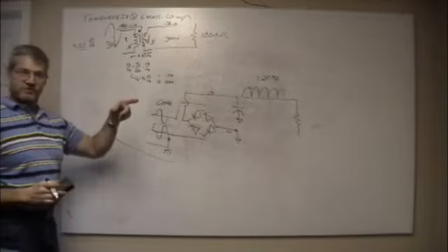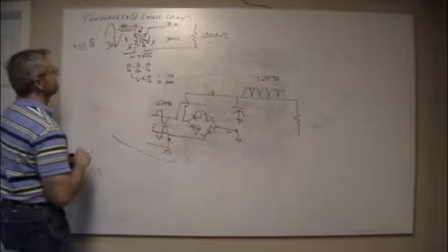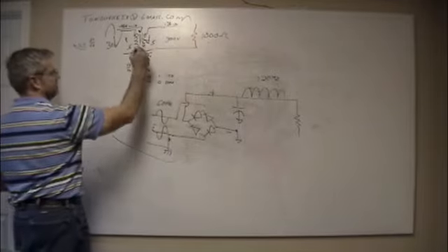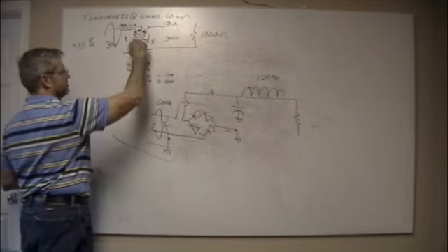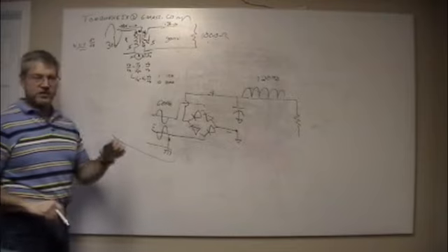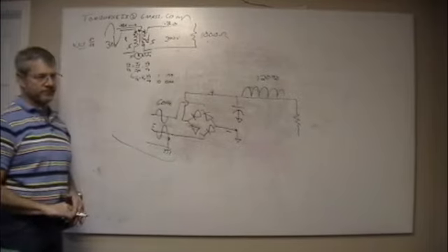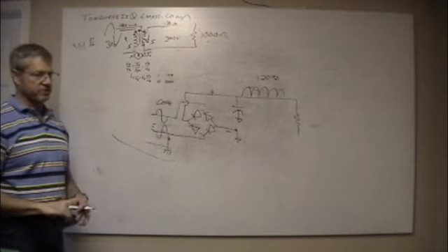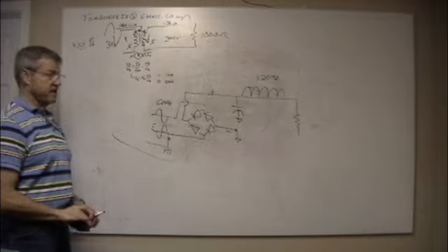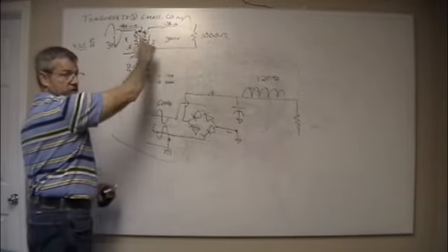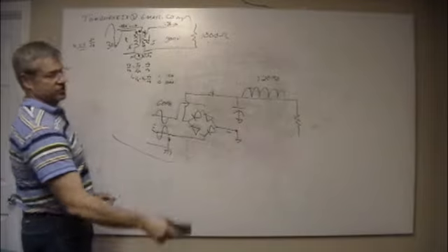Transformers are a good way to do that. They transform impedance too, not just voltage. But this coupling factor is also part of the efficiency. It's usually higher than 0.99 on a good transformer. You usually don't notice it, but once you get down to 0.96 or 0.95, you're losing energy going across this gap, and then it's a really fast drop off.